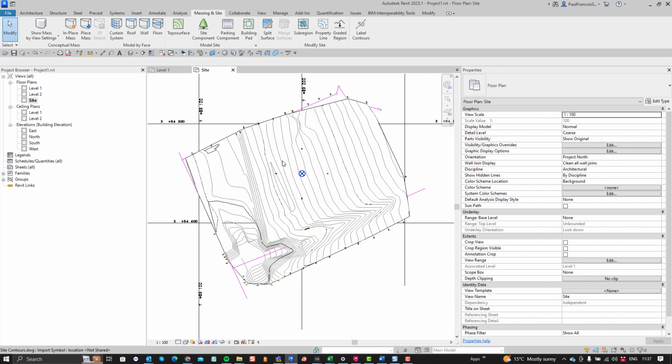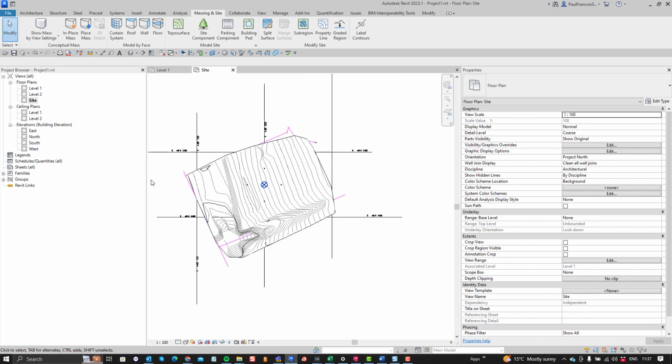And then of course from here on you can use this as a container file. You can link the container file into your Revit models, place the container file, move the container file in the X and the Y and the Z direction, and rotate as necessary, and then when it's in place, just acquire the coordinates from the container file, and that will mean that your models will have shared coordinates. But that is how you should look at a CAD file.